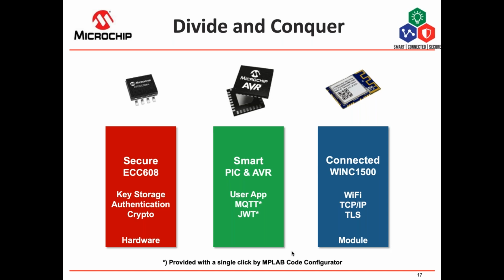And it also does all the authentication algorithms and all the cryptography all the way to elliptic curve with 256 bits, the highest level of security. What you guys use when you connect to your home banking account. That's the level of security this chip will give you. And it takes care of all that automatically in a very low power little chip that looks like a serial EEPROM. It's got only 8 pins.